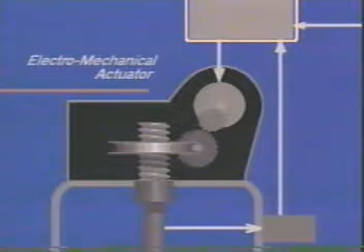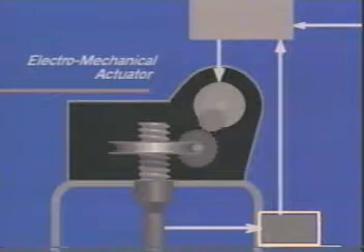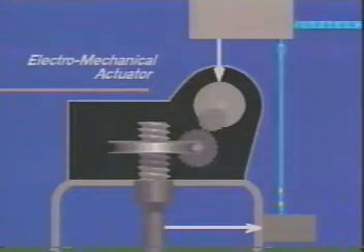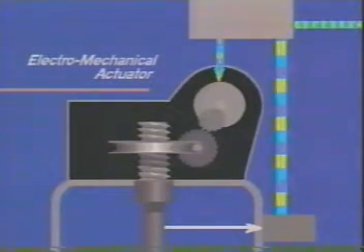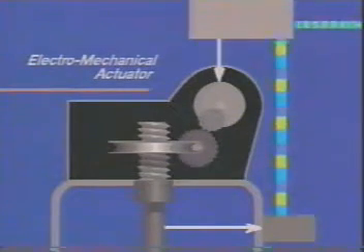An electronic positioner compares the input signal to a signal that corresponds to actual valve stem position. The signal corresponding to actual valve stem position is provided by either a potentiometer or a linear differential transformer. If there is a difference between the two signals, the positioner provides the required voltage to actuate the motor. When the error is corrected, output voltage to the motor is returned to zero.